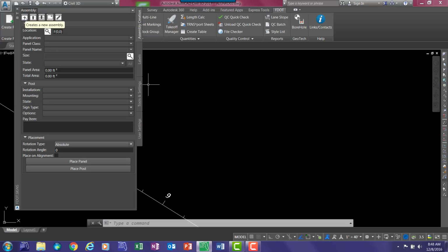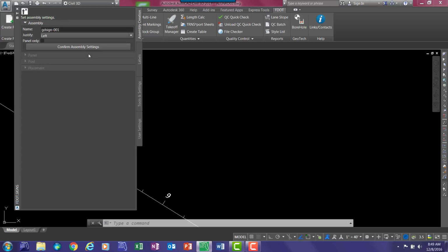And to create a new assembly, there are new icons located on the top, each with a tooltip. Get familiar with each one. Tells you the command of each icon. In this instance, we want to create a new assembly, so let's select the plus button. From here, it has a name. You can, for instance, give it a name. Let's call this stop for stop sign.